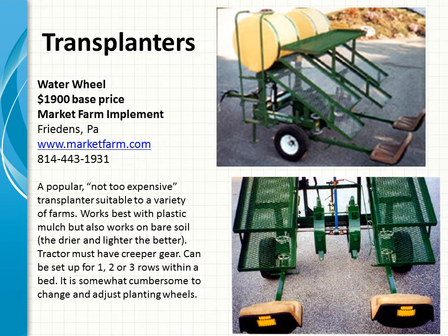If you have access to a 30 to 60 horsepower tractor, investing in a transplanting implement is the best investment you'll make if you grow large numbers of transplants for your production system. A water wheel transplanter is the best entry implement into the mechanical transplanting world. It creates the hole into which a seated worker can place a transplant while it waters the hole with the starter solution all at once. This creates a precise pattern on the bed top, which makes later hand or mechanical cultivation much easier.